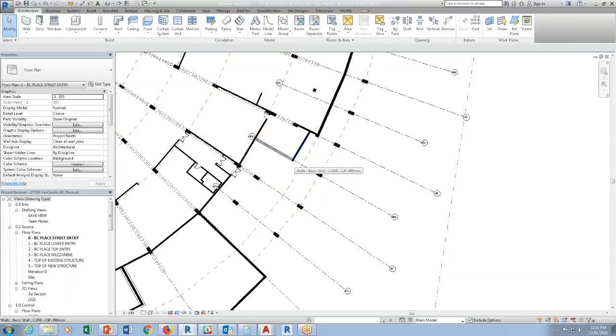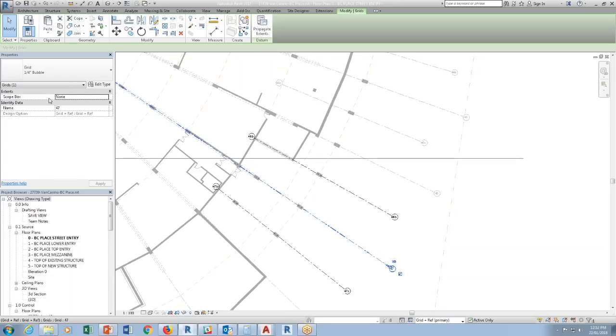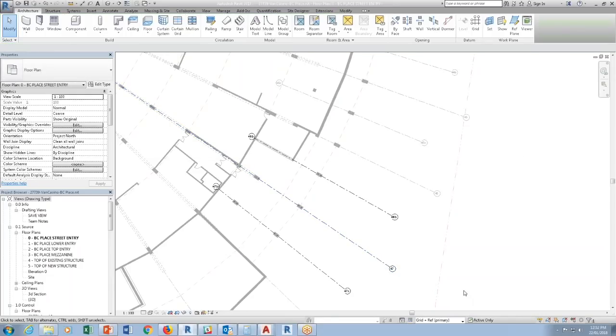Simon, if it's in a design option, it can also be in a work set, correct? Yes, you can. Okay, so we could, because when we reference other Revit models, we want the consultant's grids to be off. Yes. That's so right, we would need to do both. Yeah, that's fine. You can still do it.